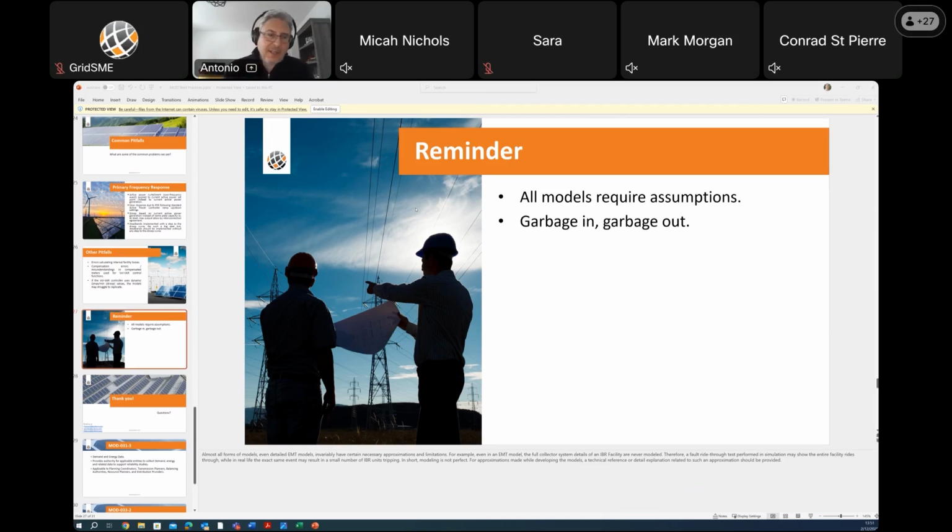And again, the other really important thing here is what we were mentioning at the beginning. Each of the models, generic models, user-defined models, or EMT models, should come from your equipment manufacturer, from inverter manufacturers, wind turbine manufacturers, generator manufacturers. They should have come with a validation report where they have done a field type test, and they compare how each of the models is reproducing the reality.